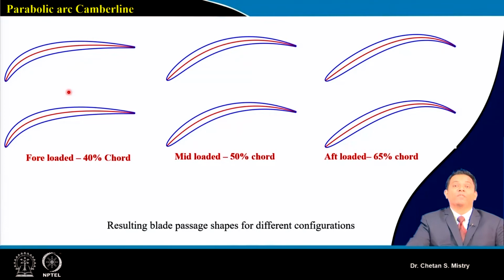Remember one thing, when we say there is separation of flow from the suction surface, that is acting like zero velocity. That means it will act like a solid body. So rather than having diffusing flow at the exit, it will give you accelerating flow. And that's where you need to play with the shape of your aerofoils. This is very important for you to learn at this moment.